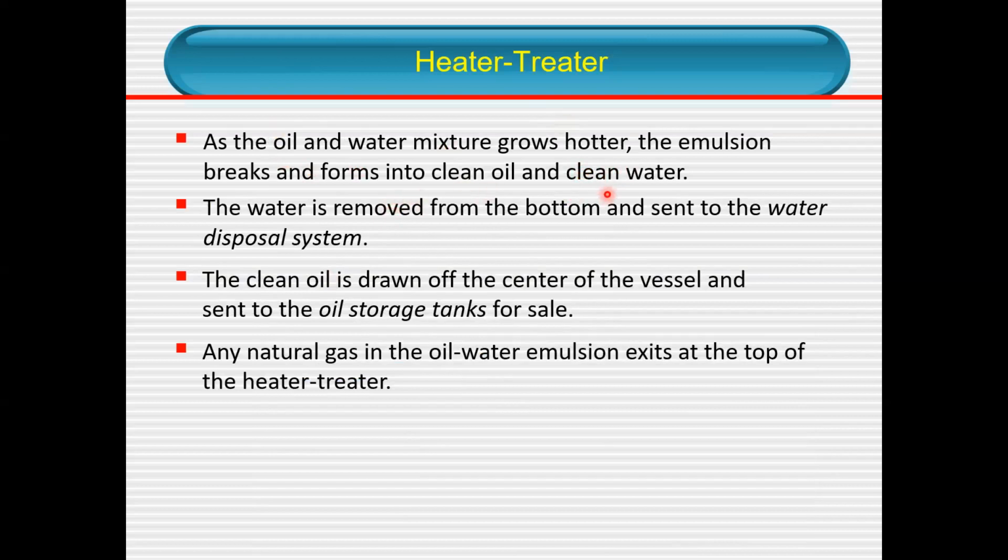Any emulsion, when you start working in the field, the first thing you can do is try to heat it. If you can separate them that way, you don't need any chemicals. Beyond that, it is all about economics, whether you need the heater or you can just use another chemical which is cheaper than the heating.